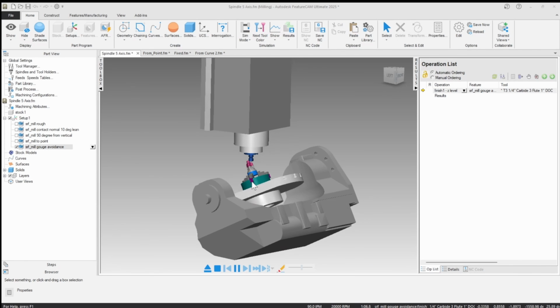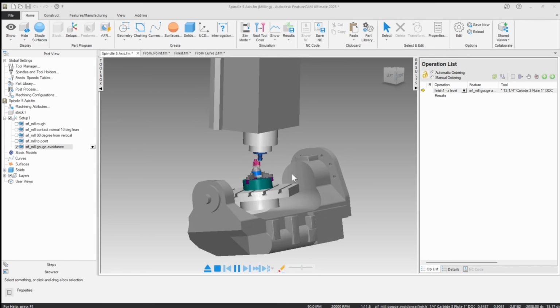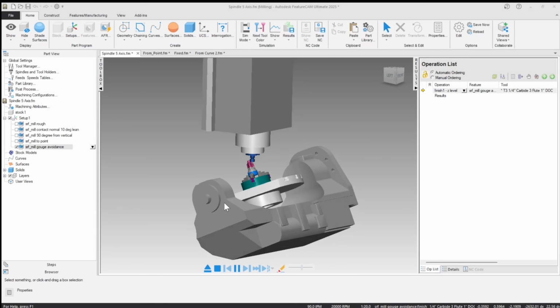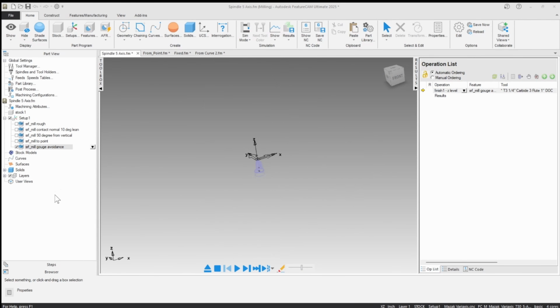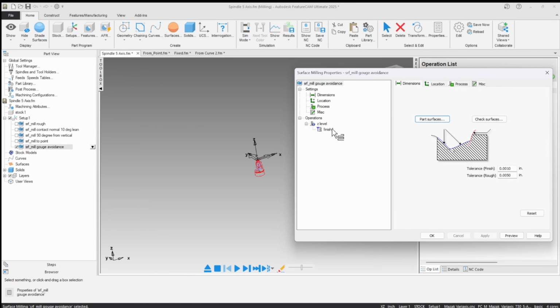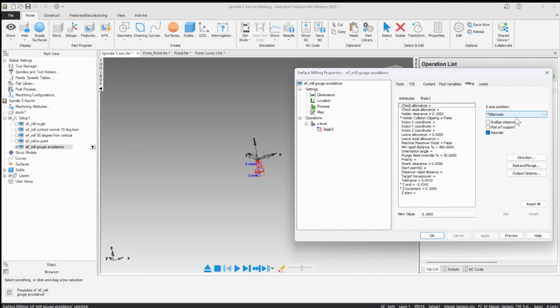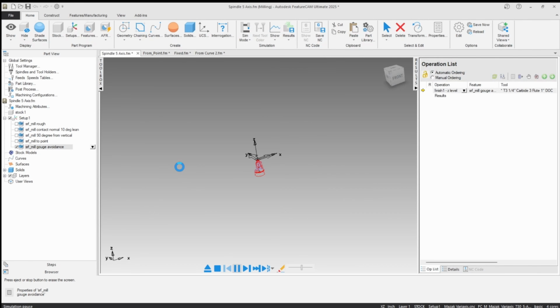So it looks like standard was going to be the answer again if we wanted the part to tilt towards us. I chose alternate, and we can see that's going the opposite way. Quickly I could just make that change, or you could watch it machine like this, however you want to do it. Just as one last reminder, in the milling tab, I'm going to go back to standard. You really need to just watch the toolpath. Alternate was the answer only in one of those scenarios; standard seemed to be the answer on the others. Recalculating here takes just a moment.